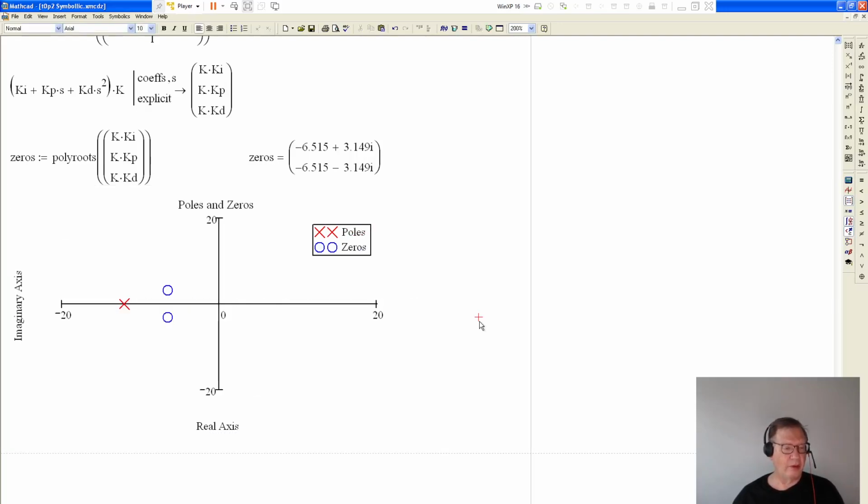Now, I have another video where I place the closed loop zeros, and if you can place the closed loop zeros right here, it won't cause much or any overshoot. And also because it's not complex, it won't cause any problems like making a zero or like a notch filter. You can actually place the zeros to create a notch filter if you know how to do it.